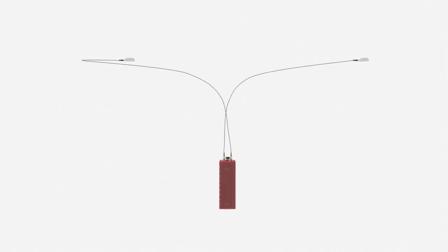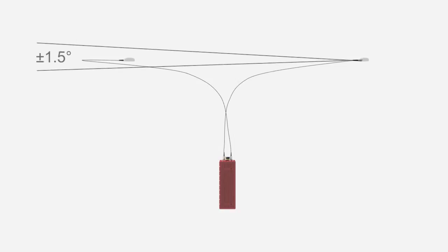The next step is to enable the secondary antenna. If the antennas are level, within 3 degrees when viewed from the front or side, then check the antennas are level option, as this will speed things up during the warm-up procedure.